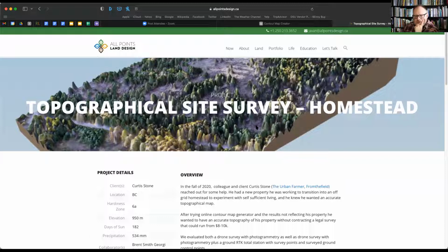And we did what's called ground control points. So I rented what's called an RTK, real-time kinematic total station, which basically, if I leave it in one place, usually at the top of the property, for long enough, will find itself in relationship to the world and the different satellite constellations to sub-centimeter accuracy. I think it got down to like half a centimeter. So that point on the entire slope was as accurate as we could get it.